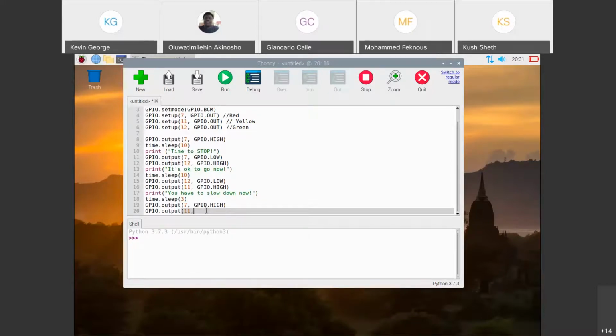So that's working with our LEDs. The next piece of hardware that you should have got with your kit is a push button. So we're going to put our push button onto our breadboard. Of course, make sure there's a gap in between so that the pins aren't shorted.